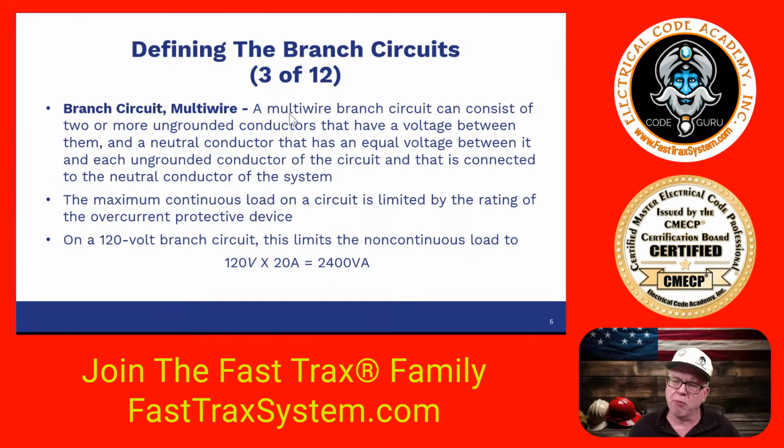It says, a multi-wire branch circuit can consist of 2 or more ungrounded conductors that have a voltage between them. Okay, a good example is a black and a red with a shared neutral. Between the black and the red is 240. Between the red and the white is going to be 120. Between the black and the white is 120. So they have a voltage between them, okay? But they also have a voltage between them and the grounded neutral conductor, okay?